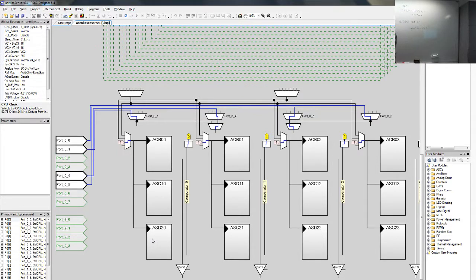So what it actually means is that the switching frequency is controlling the conductivity of this circuit, meaning it's a frequency controlled resistor, an adjustable resistor by just using the switch. So that's fundamentally why we have this kind of switch capacitor things here.